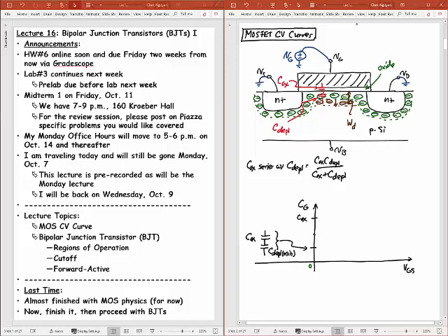And so if that's the WD for the case when I have a larger VGS than 0, and this is the WD, maybe I'll draw it right here, for the case where VGS is 0, then this is going to be smaller than that. Okay? And so if the green WD is smaller than the brown WD, then the brown WD basically means I'm decreasing my capacitance. So if I'm plotting this capacitance here, the brown curve here is decreasing. So this is going to do something like this from that point.